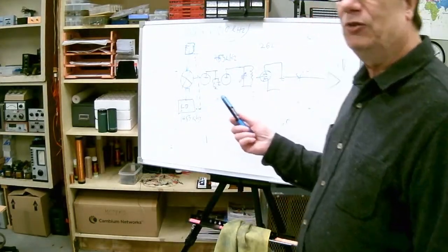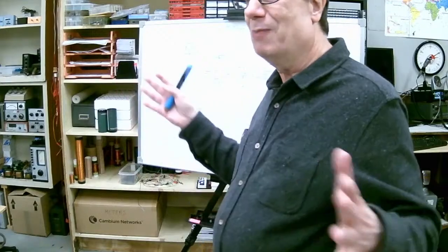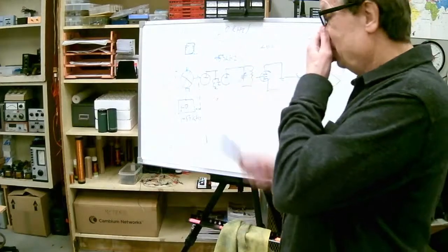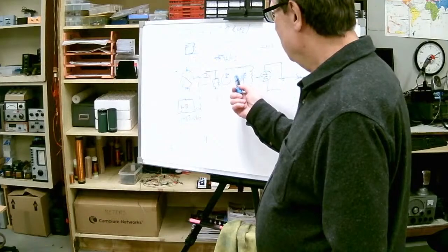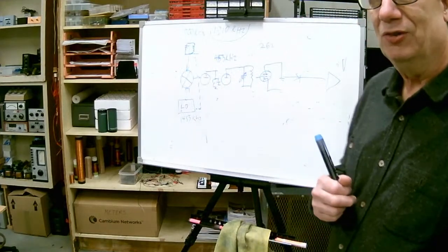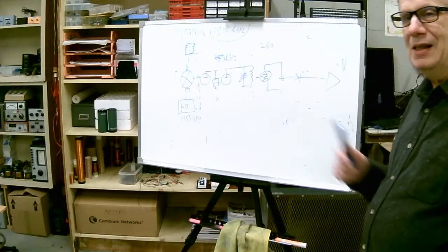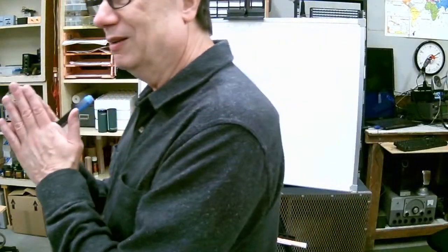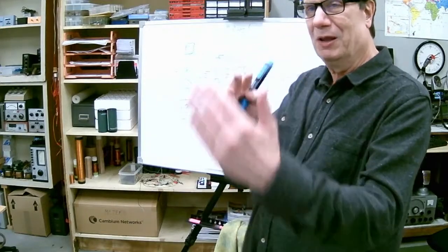The only problem is when you start going to communication systems where you don't want a lot of bandwidth, when it's super narrow, or Morse code or anything else. We have gobs and gobs of stations, especially in shortwave, just jammed together. We wanted more selectivity. So you have another issue. You go to a lower IF frequency, the image rejection is no longer as good, but you get better selectivity overall. Selectivity is the ability to separate two close stations. So the lower the IF, the narrower you can make your selectivity.